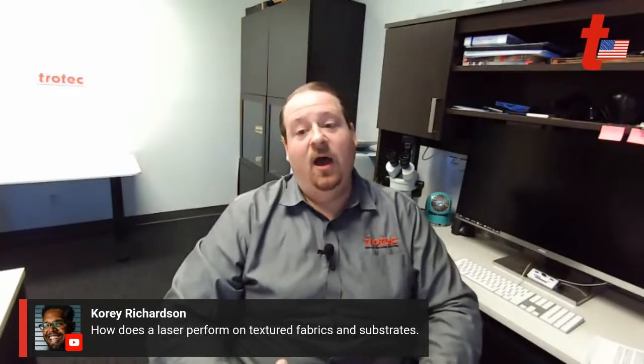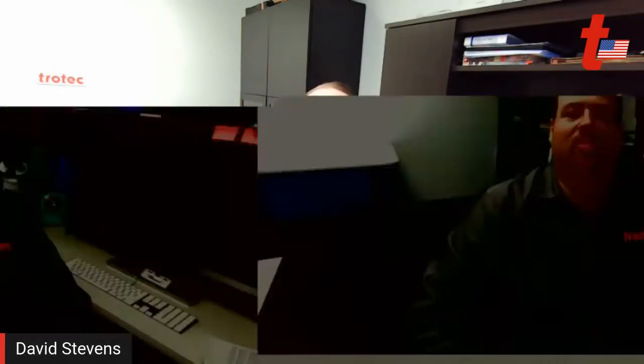How does your laser perform on textured fabrics and substrates? Great question. It depends on how much texture there is. With your textured fleeces and things like that, it usually works very well, but that texture will interfere with what the graphic can look like. It can be tricky, depending on what size or type of graphic you're doing. If you're running a larger graphic on a textured material, understand that the texture is going to ripple through your graphic, and sometimes that can be undesirable. So it's a case-by-case basis on what it looks like, and testing is typically recommended.